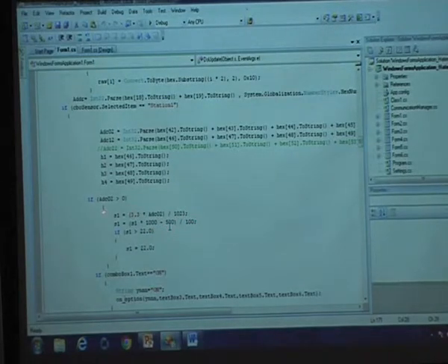So that is stored in which particular variable? That is now stored in the variable called S1. So I am storing the temperature sensor values in the temporary variable called S1 here. I repeat once again, I got the corresponding pin number 20 values like 42 byte, 43 byte, 44 byte, 45 byte into a temporary variable called ADC02. The ADC values which have been got are converted to corresponding degree Celsius, and that degree Celsius value is going to be displayed on your text box.